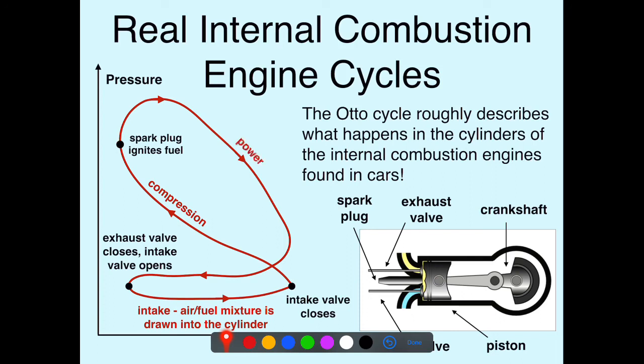Okay, this next part is called the power stroke because the spark plug ignites the fuel right here when the piston is at the top. That fuel that just ignited is going to drive the piston back down. It's going to push it way back down where the volume starts increasing again and the pressure starts dropping again. That's what we call the power stroke.